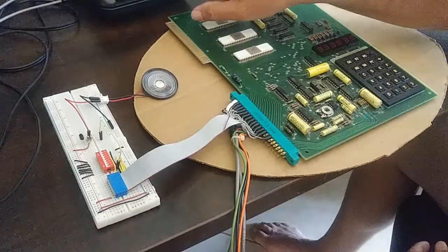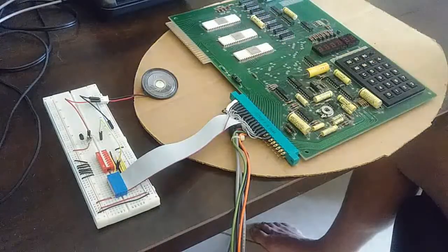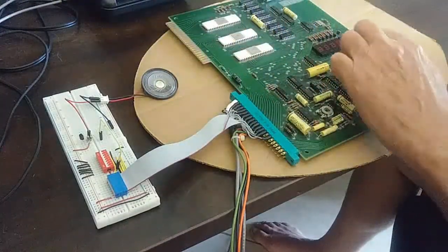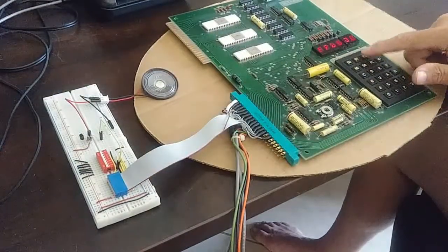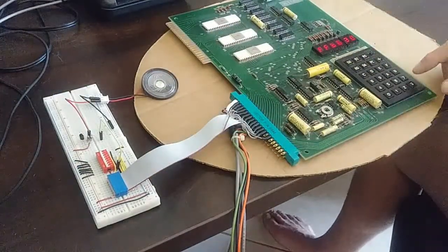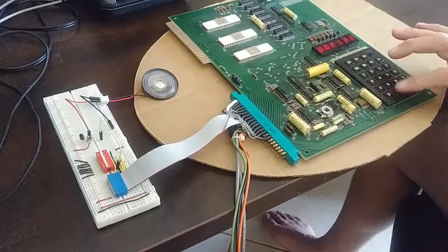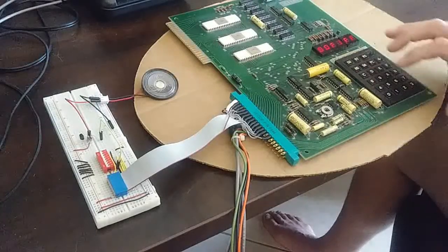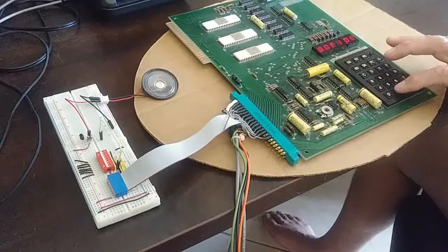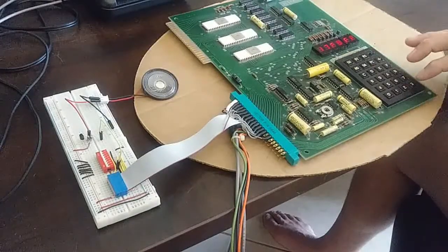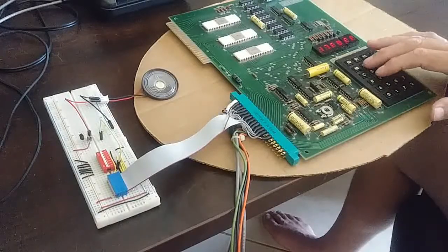Let's see, we have this. Got to rewind this all the way. And we're going to start by restoring that same program that we did in the last video back onto the KIM-1. So let's go to first address 00F1 and go into binary mode. And we're going to go to address 17F9, and we're going to put in the tape ID that we stored.